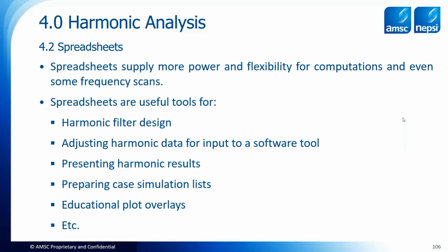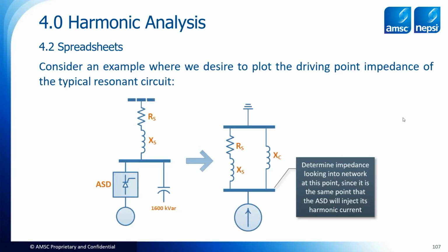How about spreadsheets? Spreadsheets supply more power and flexibility for computations, and even some frequency scans. And they're useful tools for things like harmonic filter design, adjusting your harmonic data, for getting it all prepped, presenting harmonic results, preparing case simulations, some educational stuff. There's a lot of uses for a spreadsheet, and I actually make pretty strong use of spreadsheets when I'm doing post-processing of my results. Consider this example where we desire to plot the driving point impedance, and we're going to talk about this in just a minute.